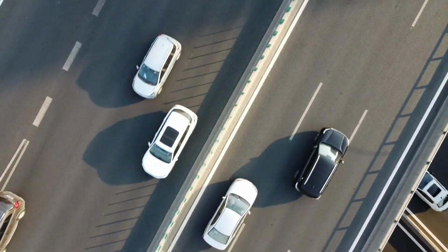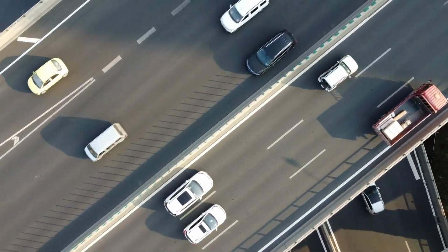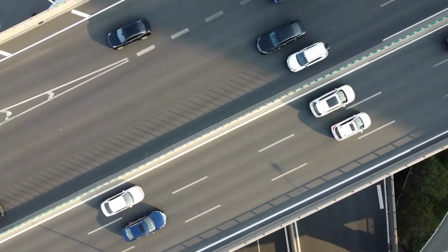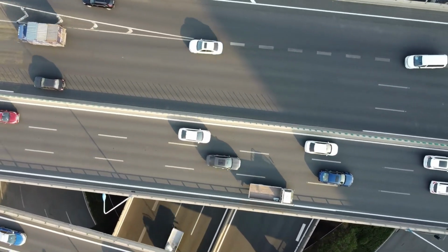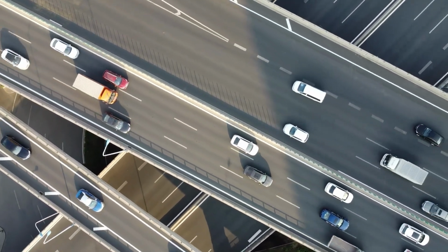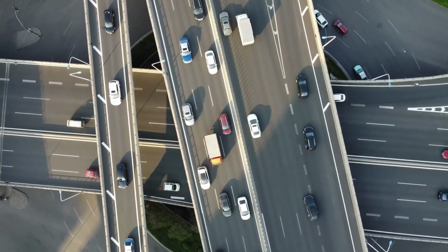In conclusion, speeding is the main safety issue along this road, especially due to its downhill alignment and the presence of a kindergarten. The speed study shows that many vehicles were exceeding the school zone speed limit. Therefore, proper warning signs, reduced speed limit, and traffic calming measures are needed to improve safety for all road users, especially children.